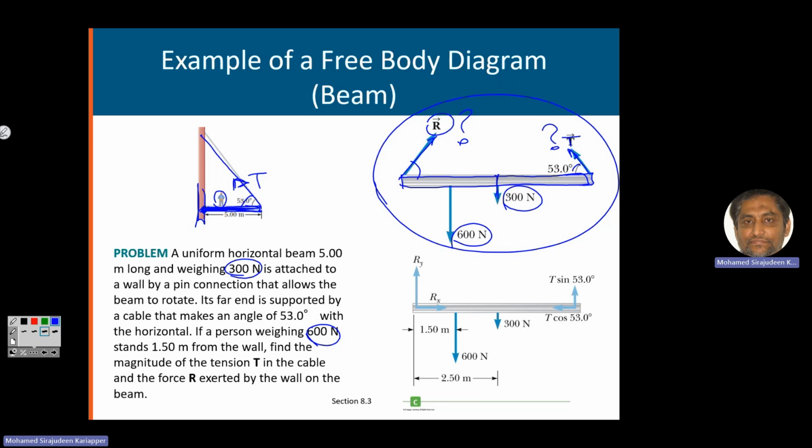Okay, we can use the net torque equal to 0, also the net force equal to 0. This will be two equations if we consider the two dimensions, x and y direction. The forces are in arbitrary direction, so we have to use both Fx equal to 0 and Fy equal to 0. So we do one thing here, further to this step. I'm going to choose my x direction horizontally to the right and y direction up.